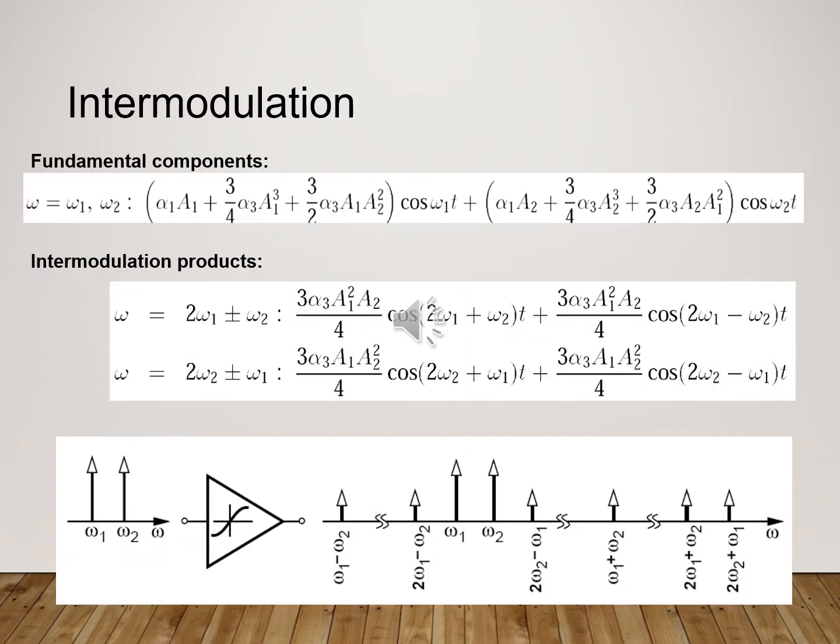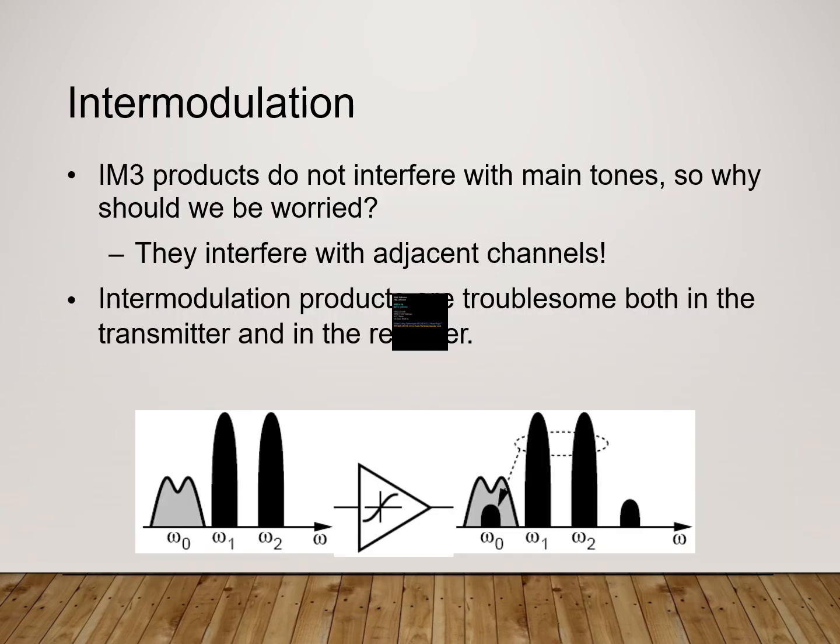Intermodulation, we also spoke about it earlier in this class. We said that when we insert a two-tone test into an amplifier with nonlinear behavior, and we have the Taylor series model, we will get some new terms. These new terms are very close to the desired signal or the fundamental, and as you can see in the slide, they are very hard to deal with, and very hard to filter out as well.